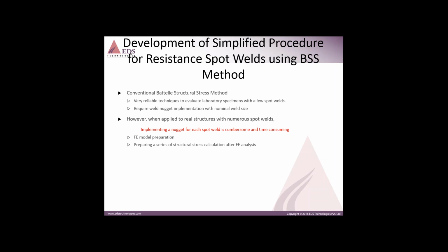So there is a simplified modeling procedure available for these types of spot welds. If you are using a preprocessor in Abaqus or Nastran, you can use a simple one-dimensional beam element. And if you are using Abaqus, you can also use point-based or discrete connectors and fasteners. This greatly reduces the modeling effort, and it will also speed up your analysis without costing you in accuracy.